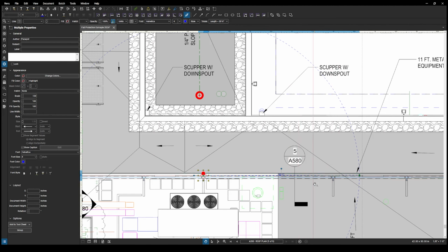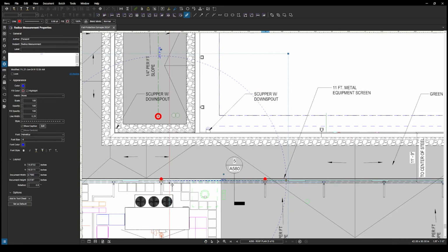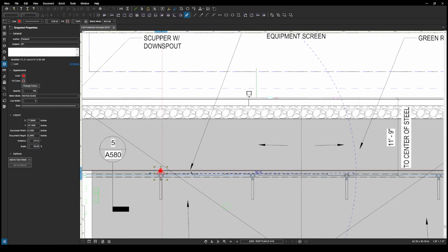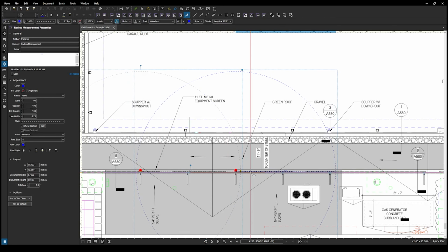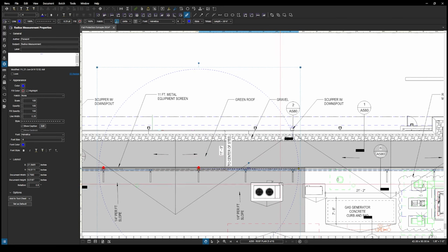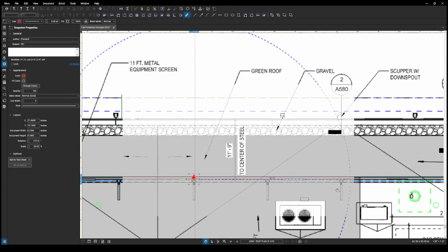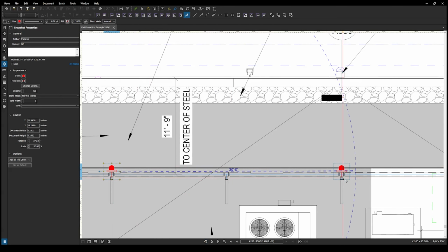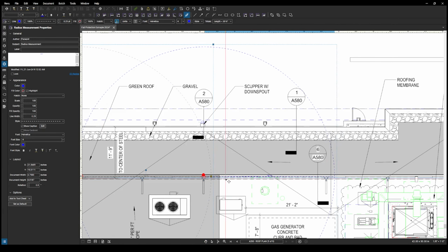one more over here. Now, if we don't know what the spacing is, we won't have a nice convenient measurement there. So what I like to do here is just add a circle with a radius of 30 feet. Basically, I know that if I place an anchor within this radius, my anchors are going to be within that 30-foot span, so there's not really any issues there.